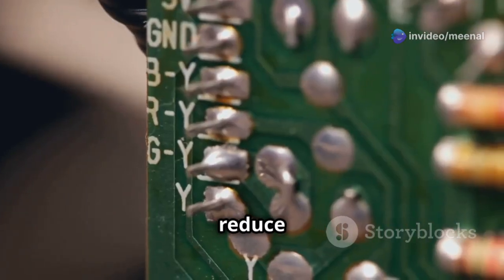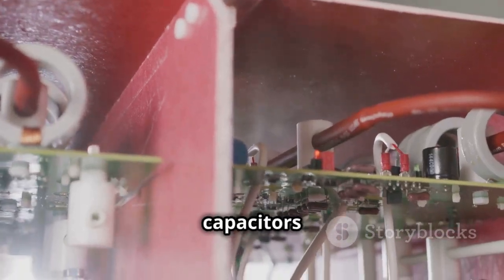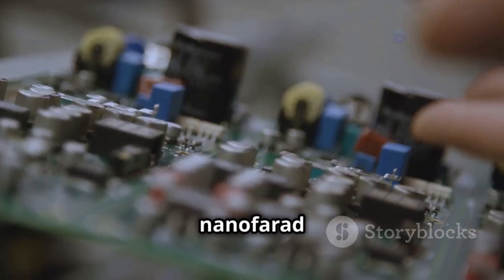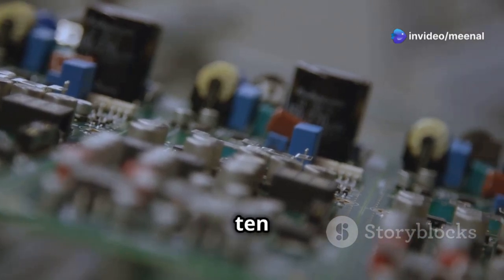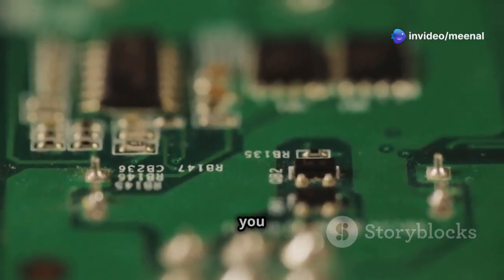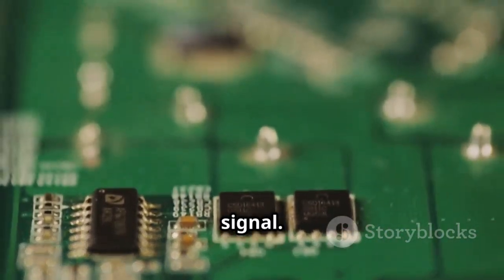Use ground planes to reduce noise and crosstalk. Place decoupling capacitors close to the power supply pins of the reset IC. A 100 nanofarad ceramic capacitor in parallel with a 10 microfarad electrolytic capacitor works well. By following these guidelines, you can ensure a clean and effective reset signal.